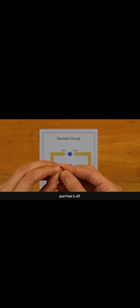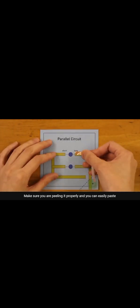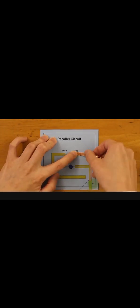You can create a template with a pen or a pencil over a sheet of paper, or you can get it printed from the market. So here I have a printed one where I have already built a small circuit on a paper, and I will follow the same path with the copper tape. So what I will do, I will cut a few lengths of copper tape and peel it off. Make sure you're peeling it properly, so you can easily paste it on the template.